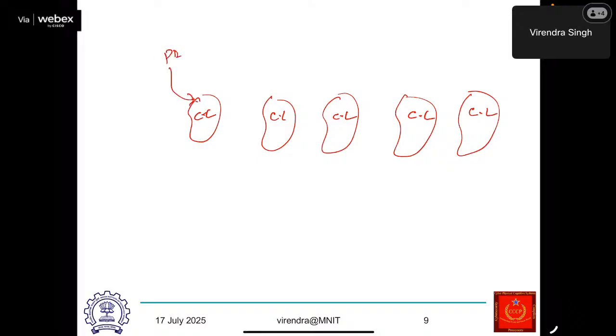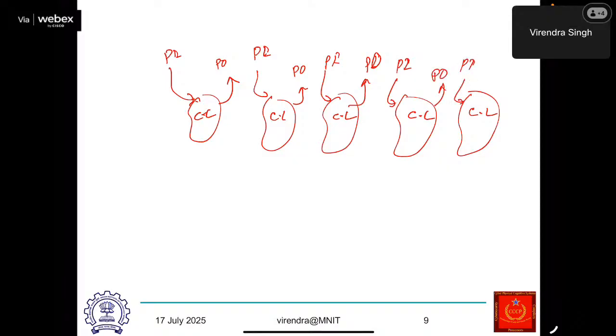Here I apply primary inputs and they give me the primary outputs. The value from the pseudo primary input, the PPI, should start from X, and it has to go to the next time frame, and the next, and the output here I ignore.